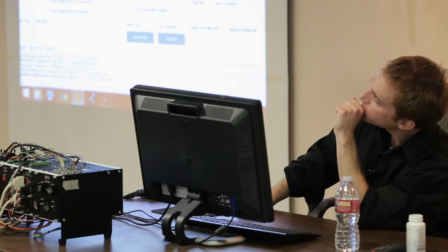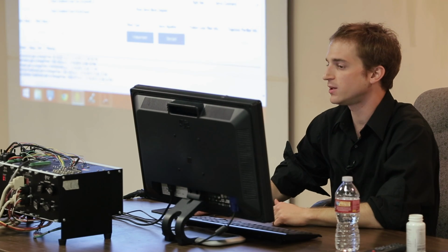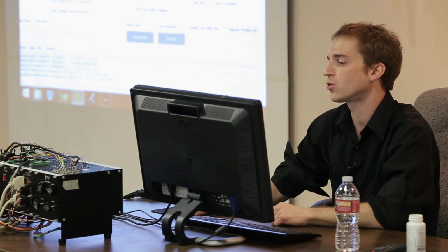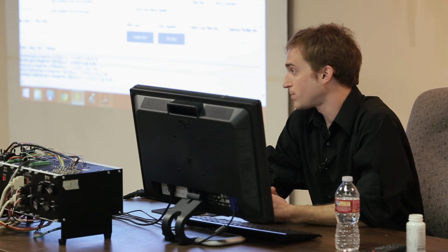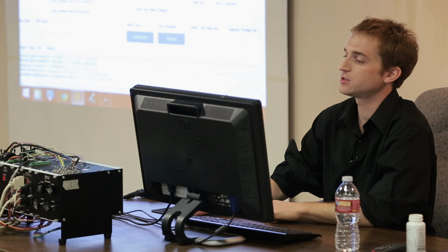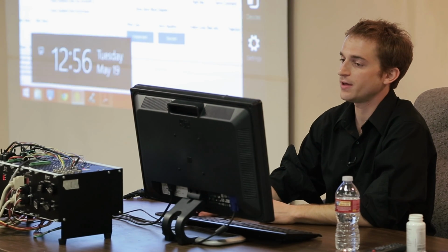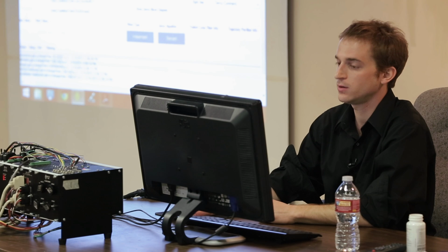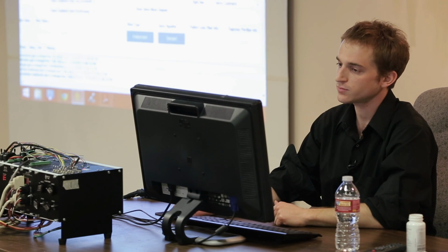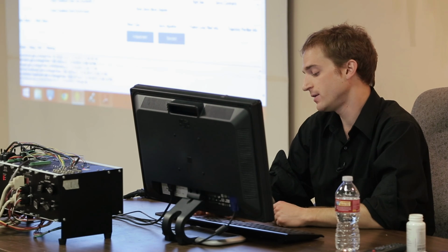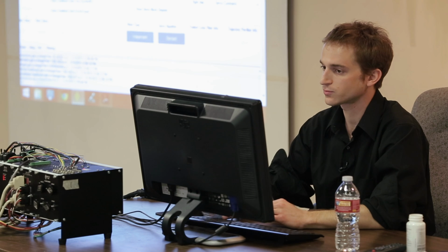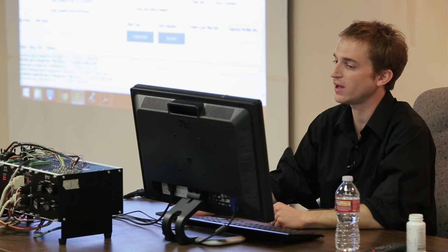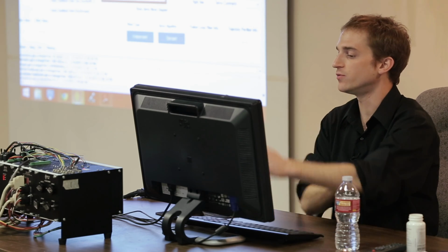So like before, I want to keep my step size between 1/4 and 1/2 of a revolution of the motor. These particular motors have 2,000 counts per revolution on their encoder, so 1,000 counts is just fine. And then I will start with a fairly conservative value of 5 on KP. This is close to the default gains. And then, generally speaking, you can do something like between 5 and 10 times the KP for your KVFB, and then I will do a step move and see where we're at.